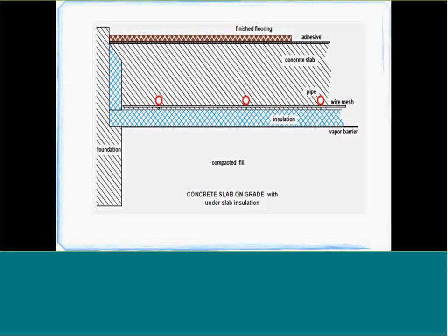I usually recommend that you insulate under the entire slab unless it's a massive amount and it's going to be cost prohibitive to insulate under the whole thing. For most applications, you always want insulation under the slab.